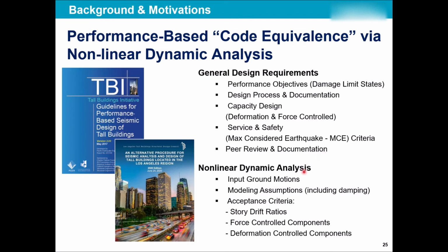On the other side, they paid so much attention to the nonlinear dynamic analysis. So instead of a nonlinear static pushover, they moved on to nonlinear, meaning they considered the nonlinearity of the material, but for dynamic analysis, not a static analysis. This time, the input, instead of simply a push in one direction, was an actual ground motion.